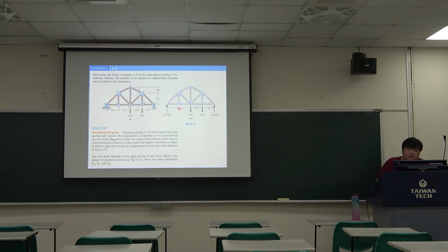So we don't calculate this reaction, because it is equal to 0 when we do the summation Fy equal to 0 and Fx equal to 0. And we have these two forces, so we can set the moment point at point A, then we can calculate this reaction. When we set the moment point at point E, then we can calculate this reaction.